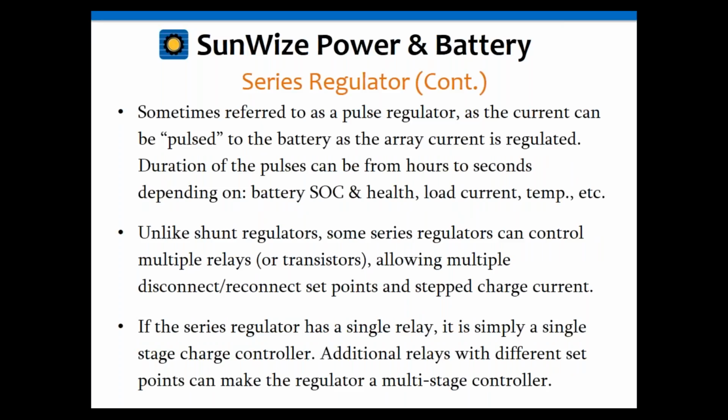Now, what you can do with these series regulators is put multiple relays in parallel. So you can get a multi-stage unit and step the charge current to the battery, unlike the shunt regulator where you're shunting the entire array, so you can only get that one stage.